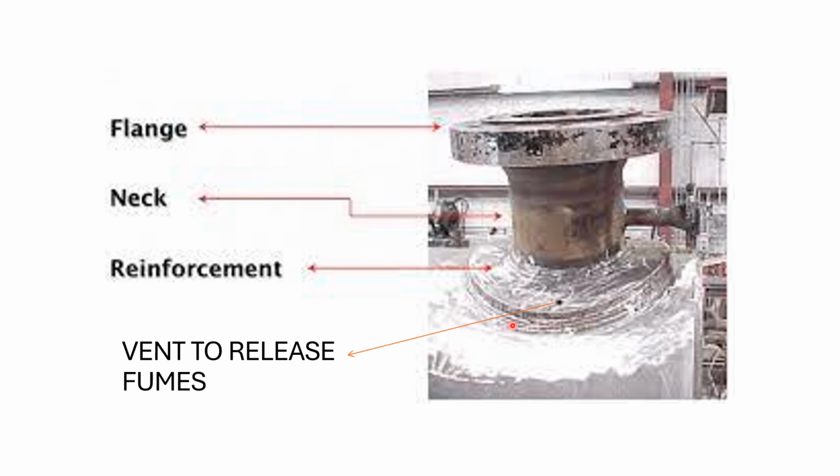Okay, so here there is a vent to release fumes. So what is the vent? What will happen when you have a flange and a reinforcement pad, RF pad, when you weld here? In between the shell and the reinforcement pad, too many fumes will get accumulated. And this fume will try to escape from the weld joint. Because when you start welding, the weld is very ductile, because it is very hot in nature, right? So this fume can damage the weld and it will crack the weld.